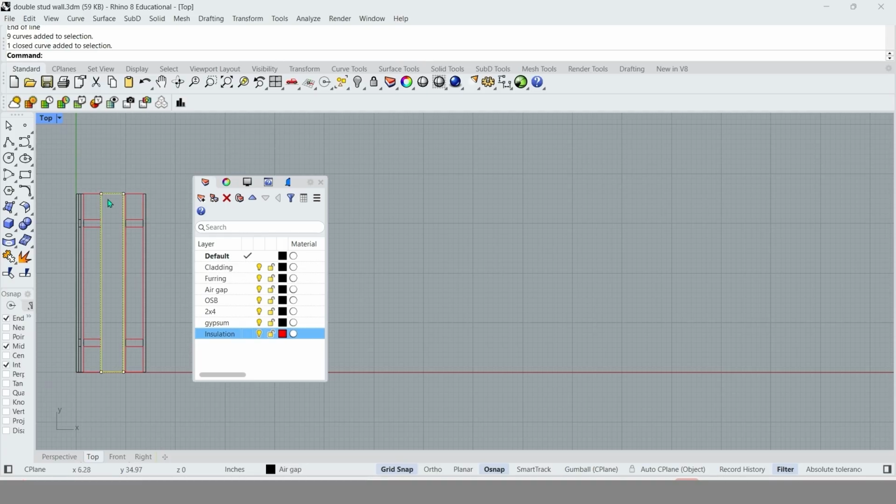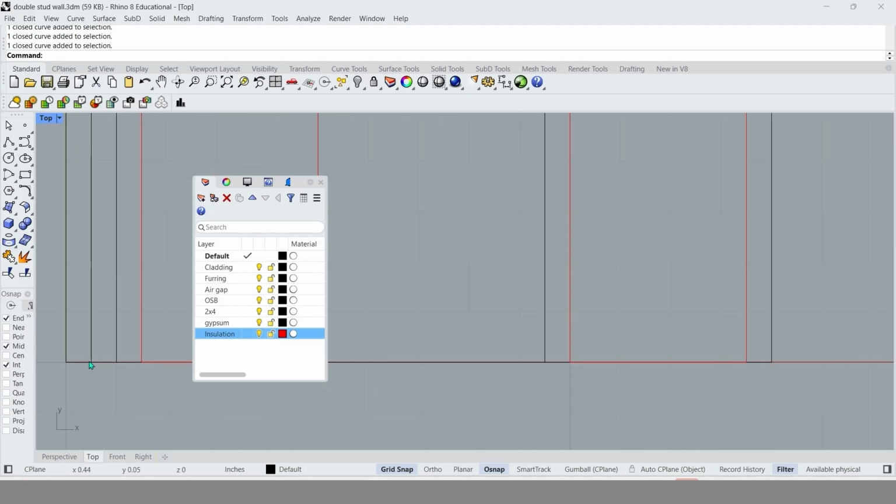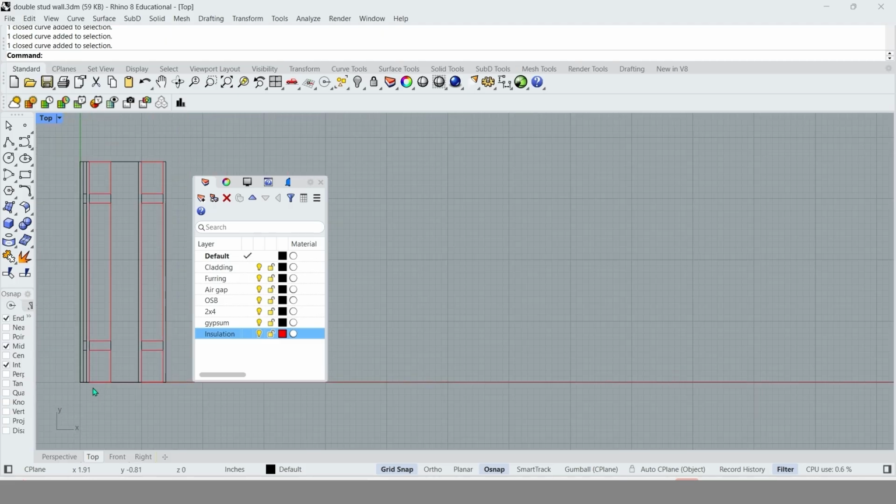I used only rectangles. You can use surfaces or closed polylines, but the geometries must be planar. Make sure that your drawing is accurately snapped to the geometries without voids or overlapping regions. Later I'll demonstrate what they are. I put the rectangles in separate layers. It is not required, but it helps you to organize the drawing.